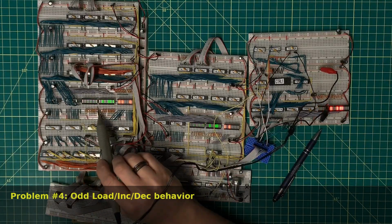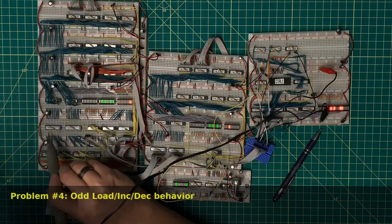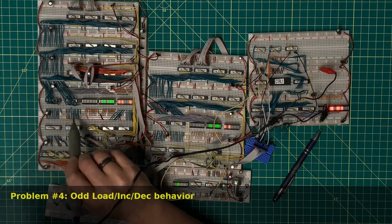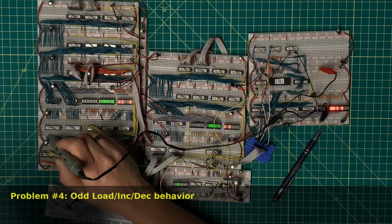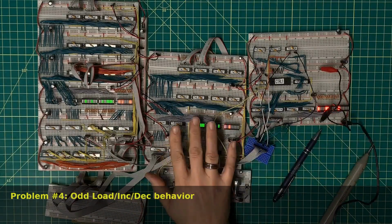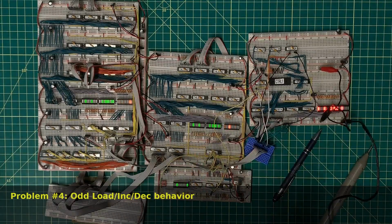This bugs me. I gotta figure this out and why that's actually doing that. Because the latch is an HCT, so if it's got a floating input, it's gonna create problems. The rest of them are LSs, which are gonna have pull-ups. Something over here is not connected well.